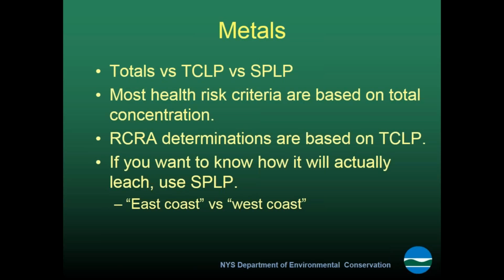And I talked to the folks in our Division of Air Resources, and at this time, the pH of rainwater has come up sufficiently in New York that it would be reasonable to use the West Coast protocol for the SPLP. Obviously, you don't need to use the West Coast procedure, but if someone does come to you and suggest it, it's not a crazy idea. We actually have made some progress on the acid rain front.